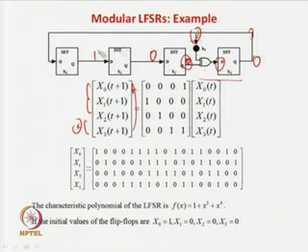So, what is the next vector here? The next vector will be 0 over here, then a 1 over here, a 0 over here, and again a 0 over here. So, this is how you get it. Now you can again find out the next vector. We know that this one is a direct control, this one is a direct control, so you get these values directly, but the third value will depend on the XOR of this one and this one. Again 0 XOR 0 is 0, and this is the feedback from here to here. So, you get the vector 0 0 1 0.